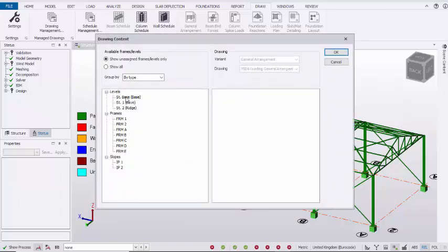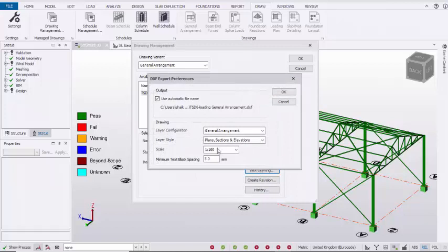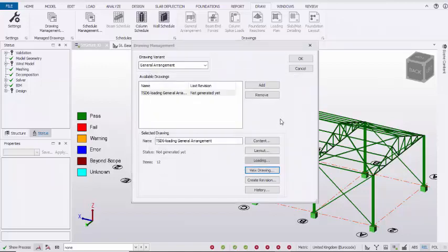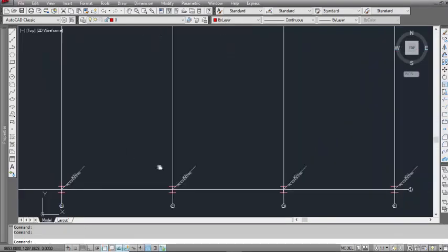Now we're going to take the base levels and ridge levels and slope levels, everything. So click on here and drag it in the side window like this. Then click on OK. Now go to the layout and OK and select this view drawings. Currently we're going to take 1:25 ratio scale and then click on OK. You can open this design information in the DXF format like this.